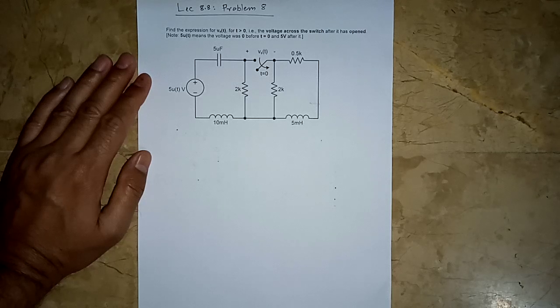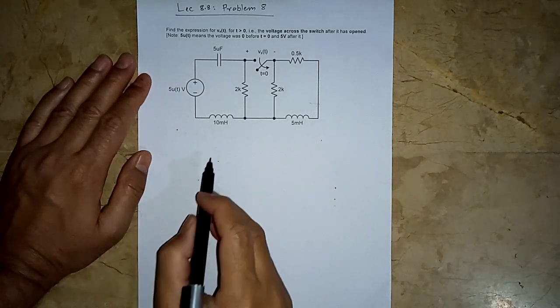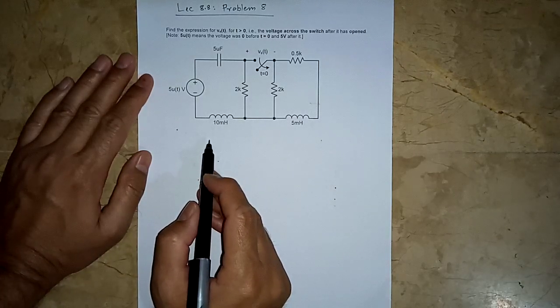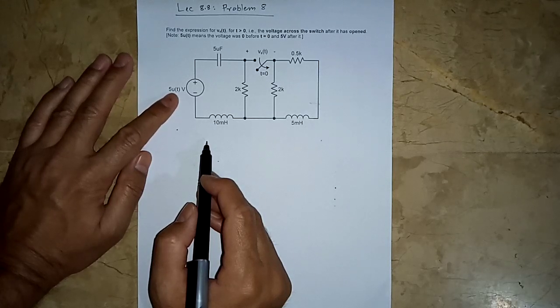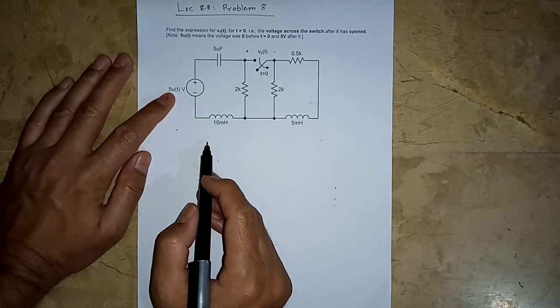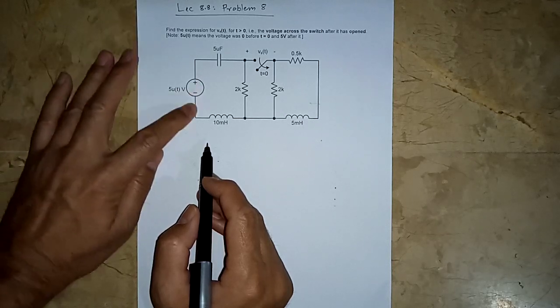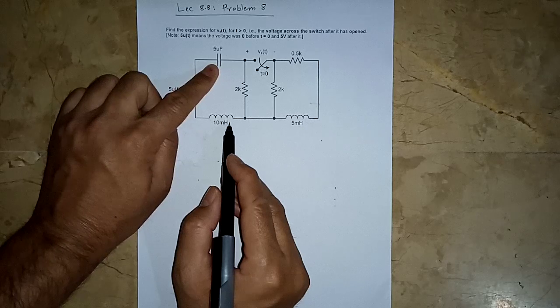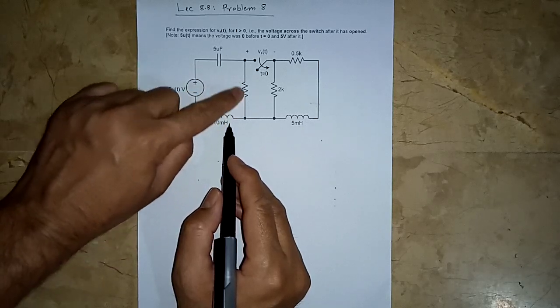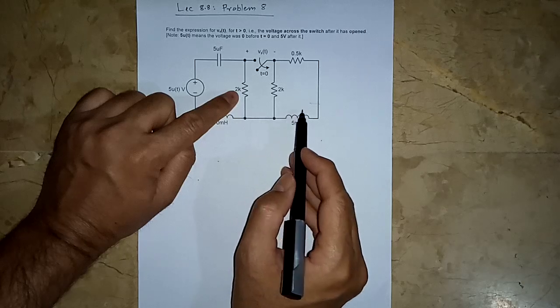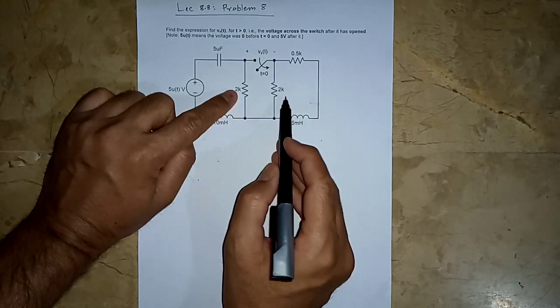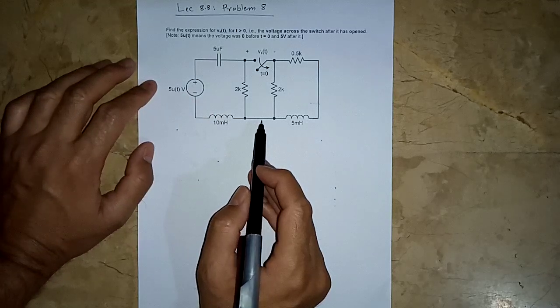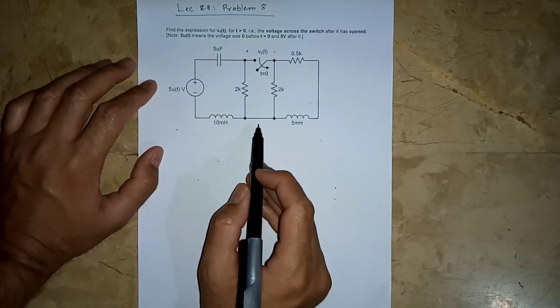Now in this question, the circuit is in steady state before t is equal to 0, and remember before t is equal to 0, this is 0 because of this u(t), the unit step function. So this is 0 before t is equal to 0, which means it's shorted out, and this is shorted out, this is open, so no current flowing here. What will be the voltage across this one? Obviously 0, and this will be shorted out, all energy drained. So there is nothing in this circuit before t is equal to 0. Everything is 0, no state.